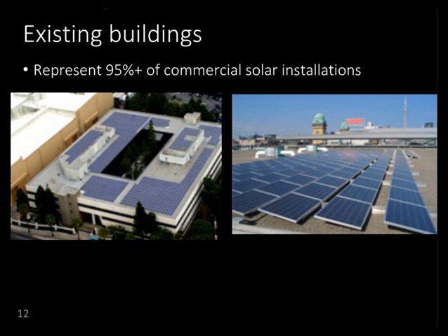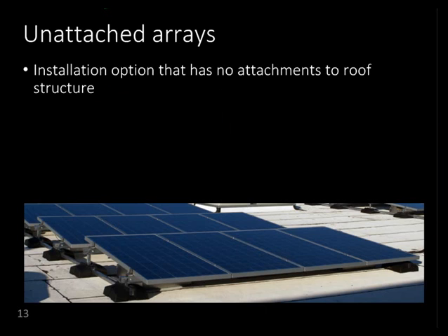So it presents an opportunity. It also presents a challenge because it means in a lot of cases working with existing buildings that weren't originally designed with solar arrays in mind. So that means you're dealing with existing roof surfaces, existing framing, and trying to interface with that in design of your solar array.